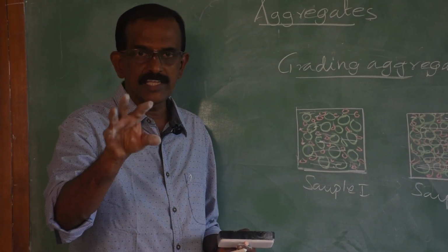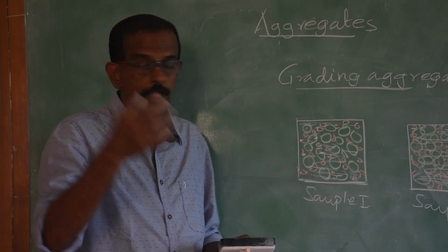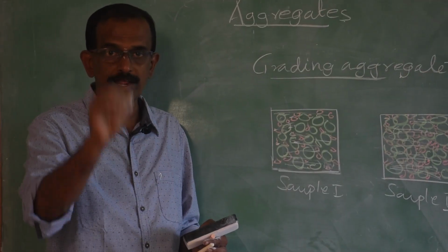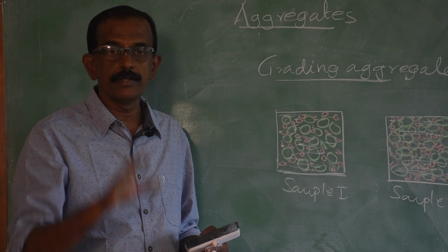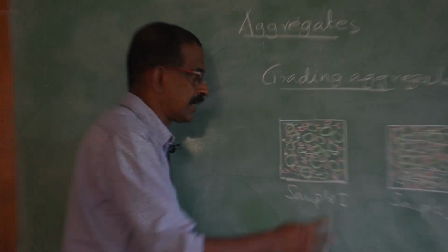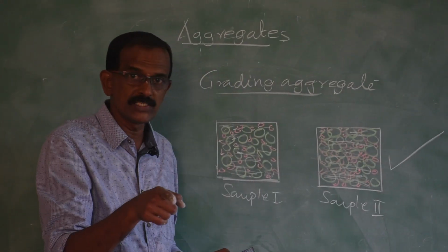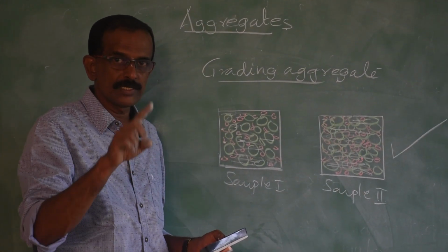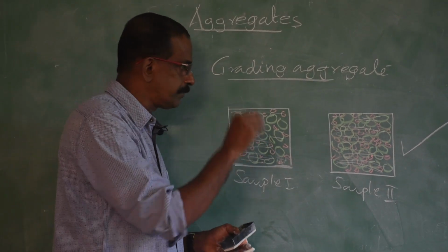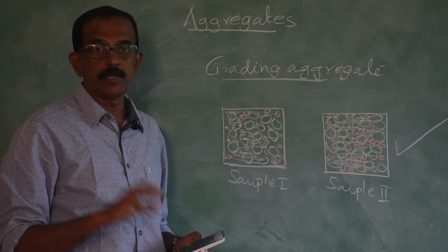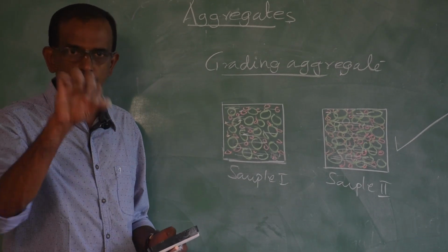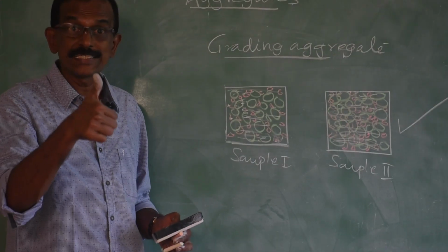So, if you use maximum cement, cost will be high. If you use maximum water, you understand like this, if you pour more and more water into cement or concrete, strength will decrease. So, here maximum cost and less strength, whereas here voids are minimized by using different sizes of coarse aggregate and different sizes of fine aggregate. There, to fill up those minimum voids, only minimum cement, not less cement, minimum cement and minimum water is used. Minimum cement means cost is less, minimum water means strength is high.